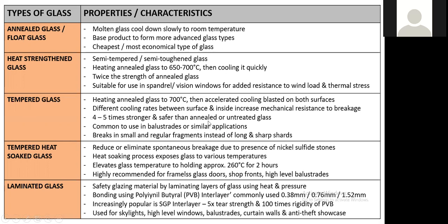Sometimes we have larger windows, larger screens, and also larger aluminum doors, glass doors, then we can use the tempered glass. It breaks in small and regular fragments instead of long sharp pieces.